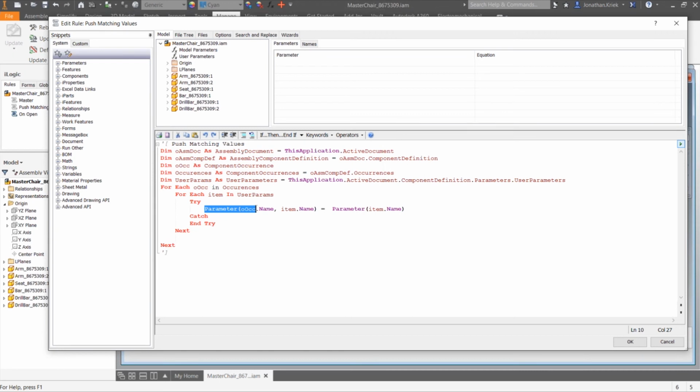That's a really quick, very simple function that enables me not to have to dive down into components constantly, or remember or hard code the names of those components, which may actually change. Remember, we're using a project-specific file name, so that becomes more difficult to target, whereas the normal iLogic way of changing parameters is harder. So this just copies those values down from this assembly to those components, if the name matches, of course.